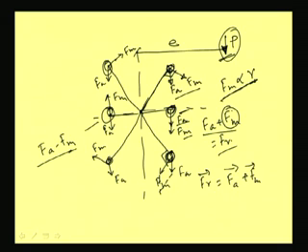Again this theta depends upon the position of the rivet groups. Theta is going to change. Here you see it is becoming less, meaning theta is going to become more, so the resultant will become less. And here also theta is becoming more, so the resultant will be less. So, we will see that for this particular case, this rivet and these rivets are going to exert more forces. So, we have to calculate accordingly and see how much load is coming into those types of rivets. So, how to calculate the resultant forces, let us see.